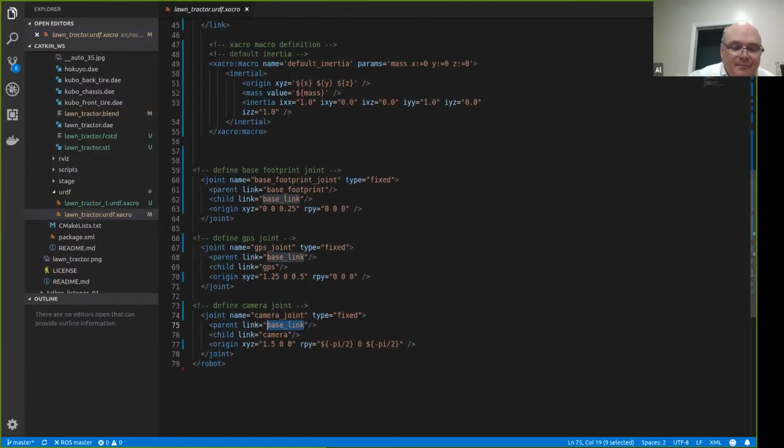That's how you're visualizing it. You want it to go from base link to the camera, and that's 1.5 meters in X. Your Y is 0 and your Z is 0, because your base link is already about 0.25 meters high as per my current configuration. So according to this, your camera is exactly level with the center of your axle. Yes. Okay.